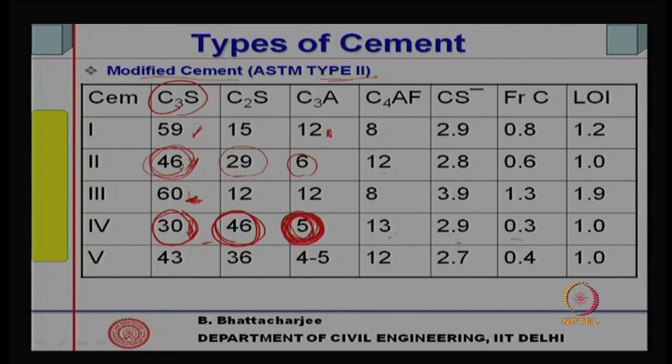So, where you do not want that kind of heat of hydration, only low heat of hydration, but you want some strength development, there you will be using this, because this will have very slow strength development. You have less quantity of this and you do not grind it too much. So, you will have lower strength development. We will look into the strength development sometime later on. This one has a very high early strength, but later strength is not good. Even that can have problems related to durability. But at the moment, this was the purpose of rapid hardening cement, where you want early strength.